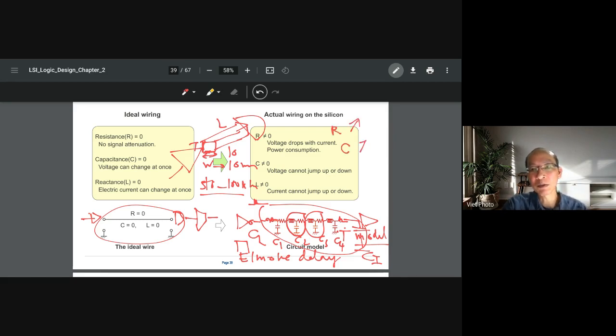C increases too, because the capacitance is inversely proportional to the distance between the two electrodes, which in this case is the wire. And you have the coupling capacitance: one wire here, and another wire coming here, running in parallel. Another wire runs parallel here, so you have a cap here, and that's another one. And then you have the cap, C.